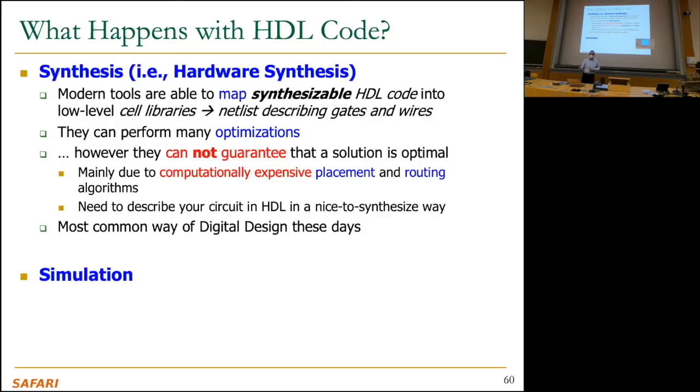So there's a very large portion of digital design that's automated today. But there's a smaller portion that's really important, that's essentially either semi-custom or full custom. You may actually hear the semi-custom and full custom terms. What does this mean? Basically, you go and change things by hand, by looking at it and actually changing the gates. Oh, I want to implement this gate as opposed to this gate, even though the tool implemented some other gate. So there are portions of the design today where you have to do this because the tools are not good enough. You're going to do that in the lab somewhat to learn, so that's a good way of learning.